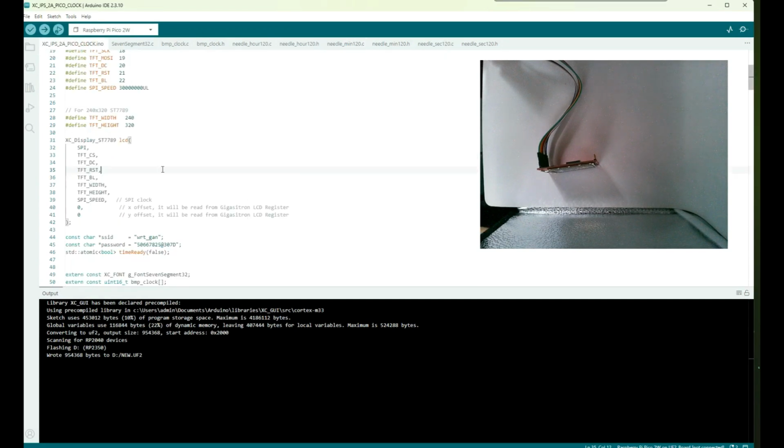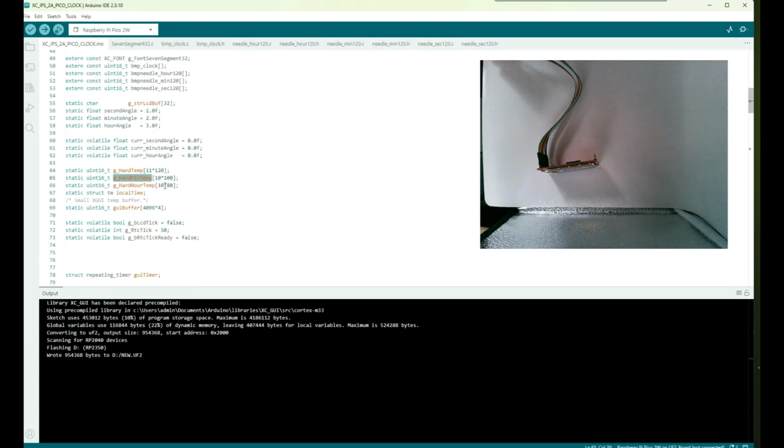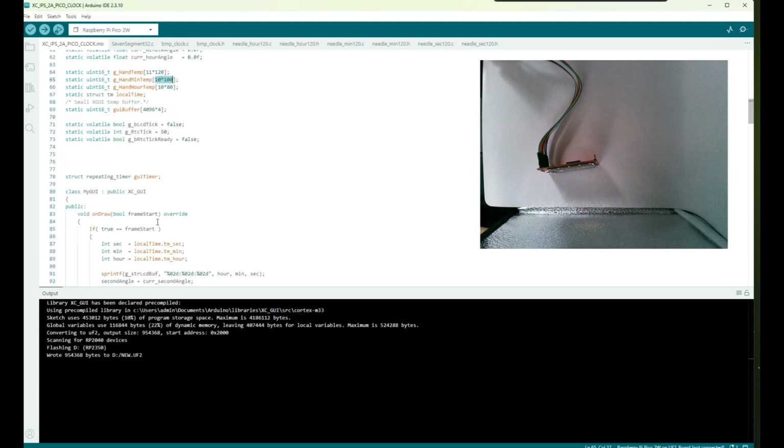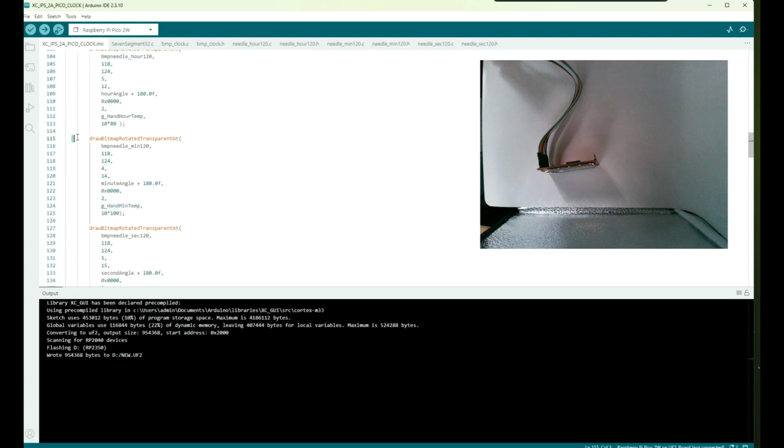The first two values indicate the image width and height. Because the image uses RLE compression, the bitmap rotation function requires a temporary buffer to decompress the image before rotating it. Make sure that this buffer can hold exactly the image width multiplied by the image height.